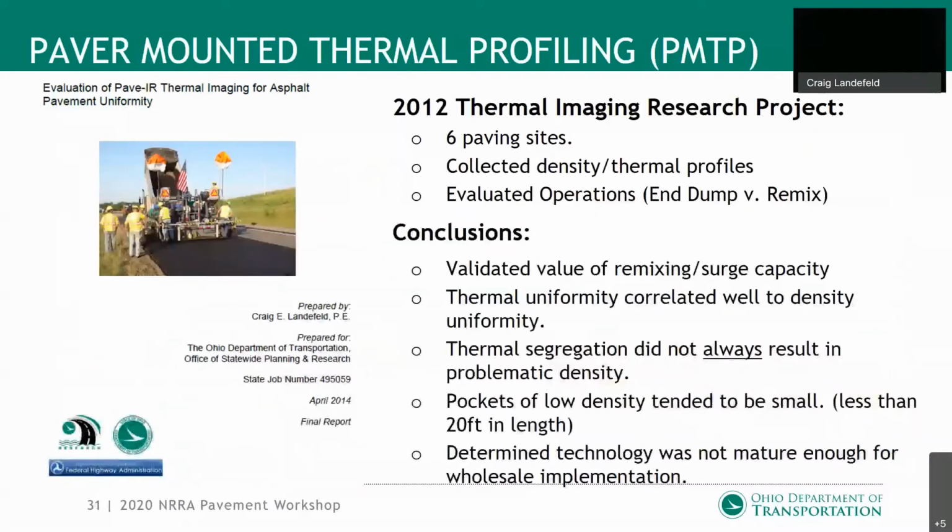So kind of moving out of the RDM arena and talk a little bit more about thermal profiling. So what kind of led us here? In 2012, ODOT did a research project that I did for an in-house project where we looked into the Paver IR unit that had come out from MOBA. We purchased one. It was one of the original bars, and we mounted it onto a paver. And we went out and the contractor paved with it on 6 different projects. We collected density profiles with a gauge.